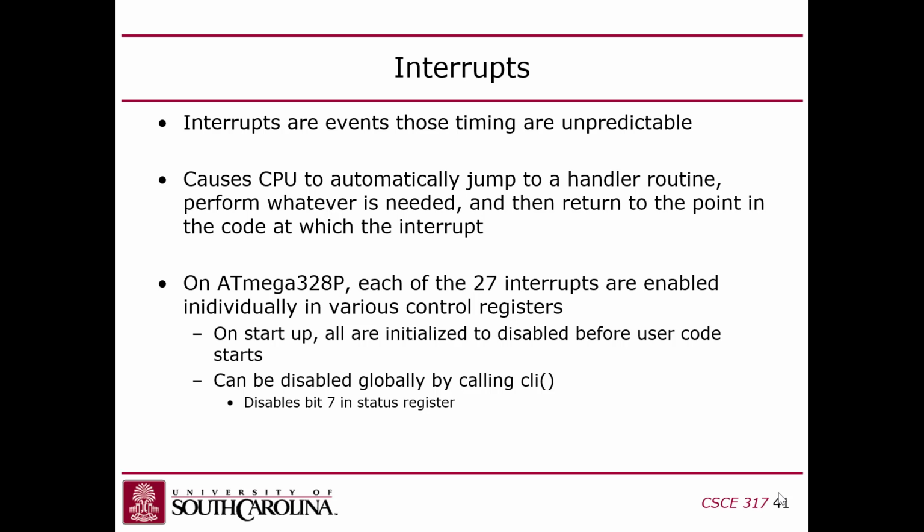So there's a second USB cable that you'll plug directly into the board, and you plug that into your machine, and Linux will detect that as a UART. And then it will create a TTY for it in /dev. So there's a /dev/ttyUSB0, which you can connect to a terminal emulator. In our case, we're going to use PicoCom, which is a terminal emulator that allows you to interact with the board over a terminal interface.